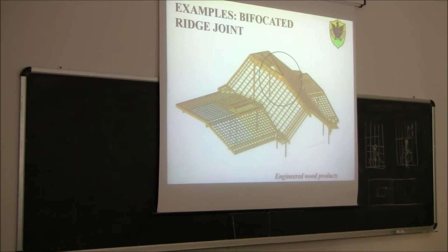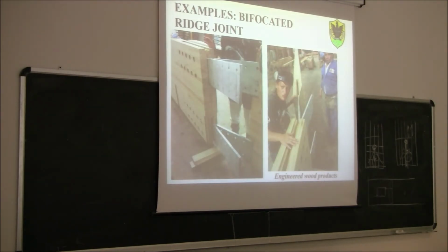Well, if this connection here was a pin, then the system would basically probably be labile. So it would be unstable. So this joint here must be rigid. Okay? So how did they make a rigid joint? Look here. So this is basically the main beam, and here there are the forks, 1 and 2. In order to be able to transfer the bending moment, of course, if you want to design a rigid joint, you need to be able to carry the bending moment. How can you carry the bending moment?